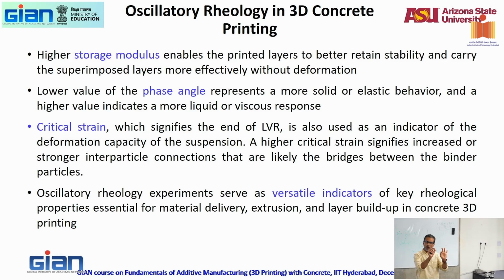That's why oscillatory: small perturbations in strains or stresses. You can do shear stress sweep, strain sweep, or frequency sweep. All the examples I showed you were stress sweeps. You're sweeping from 0.1 Pascal to 1000 Pascal, or whatever that range of stresses is, at very small frequencies, very small amplitudes. You can do the strains from 0.01 to 10%, 100%, 1000% strain at very small values. So you're not doing any breakdown, any structural damage.